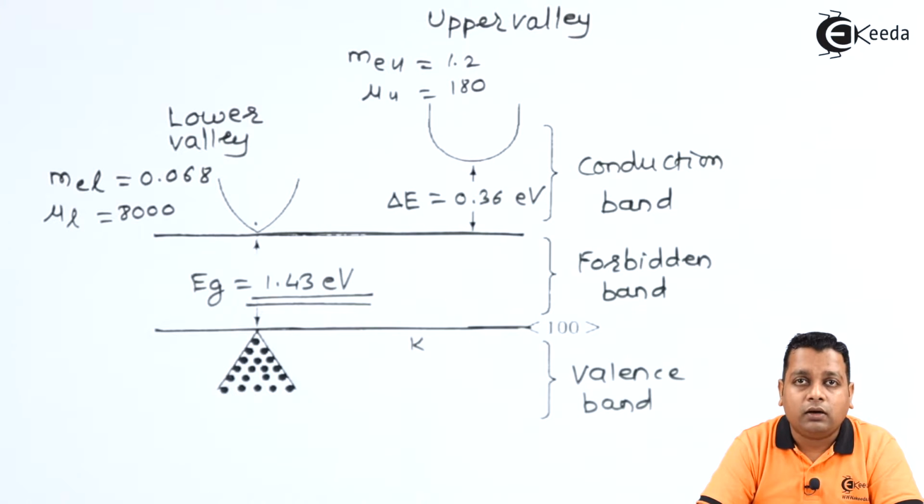Now we know that the current is constituted by the flow of the electrons. So the flow of electrons possesses good mobility. When the mobility is decreased, it means that the flow of electrons has been slowed down. Therefore, there will be a lower drift velocity of the electrons. Therefore, there will be a lower current production, lower cross-sectional current density with respect to the bulk device, and finally we can have a negative slope on the curve for electric field versus current density.